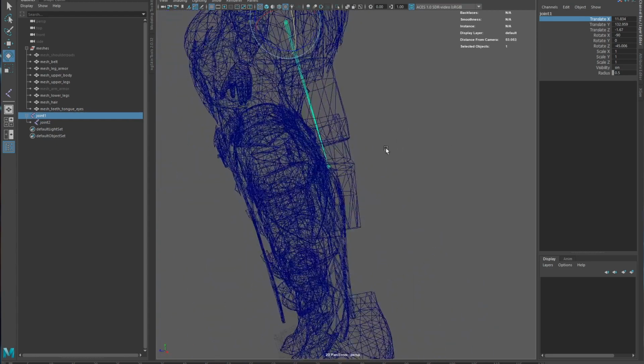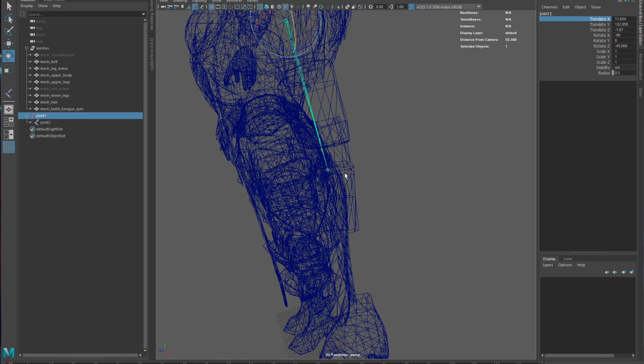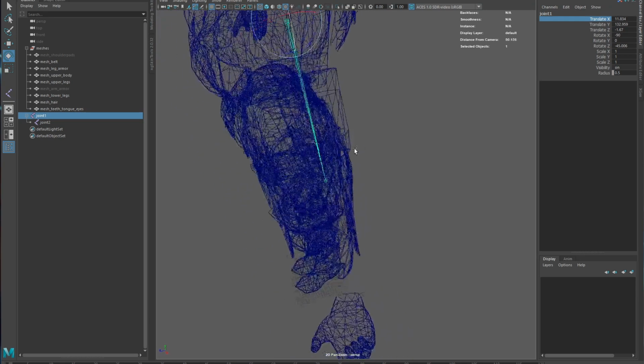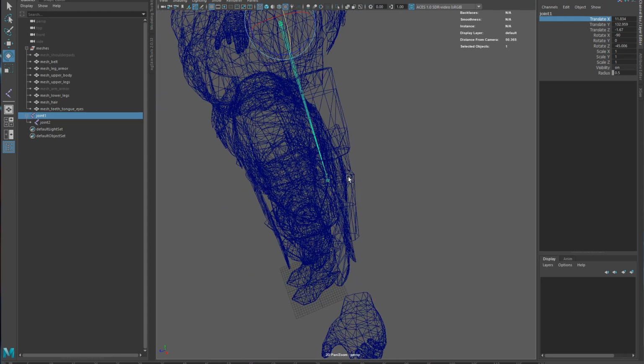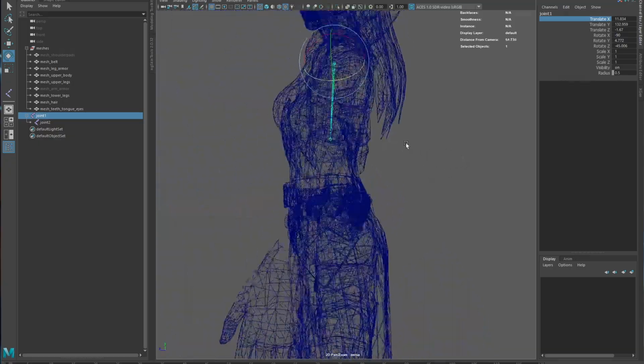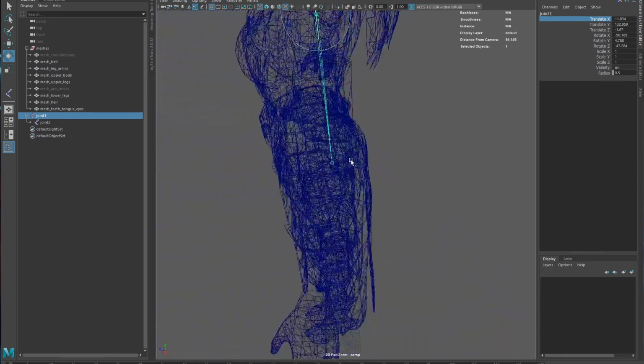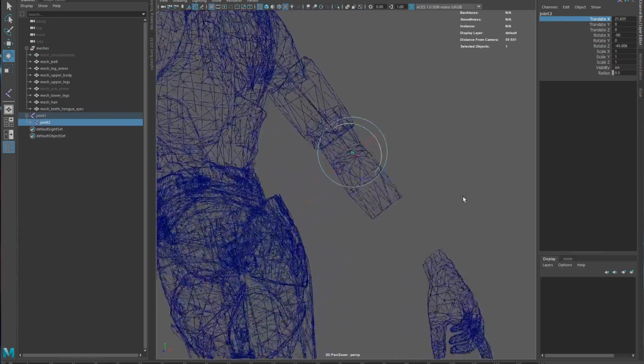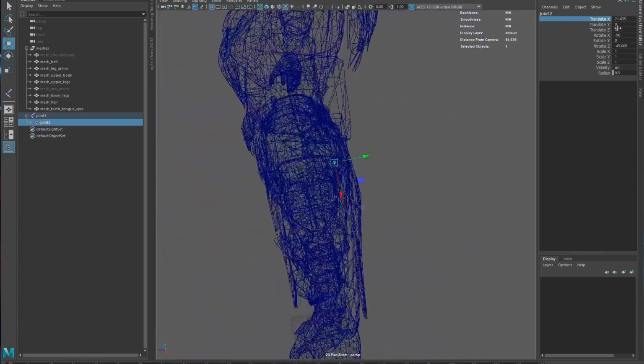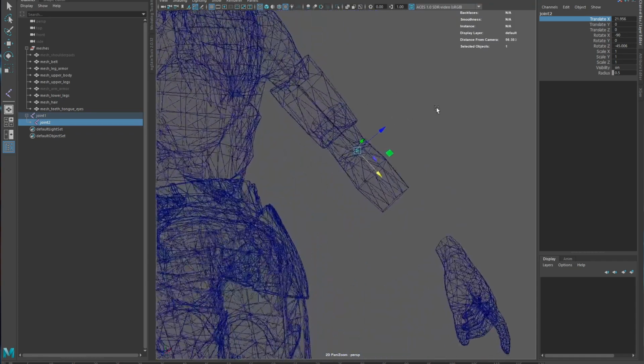But now, and this is why I don't like doing that click, click, click method, because it gets really hard in that method to start doing things. You have to constantly reorient your joints. Whereas here, I know that my elbow, I want it a little bit further back, right? So I will do this to rotate the parent joint. Also, I can look at it through this angle and see that it's not quite centered anymore. So let's do that. And maybe I want it a little bit longer. Okay.